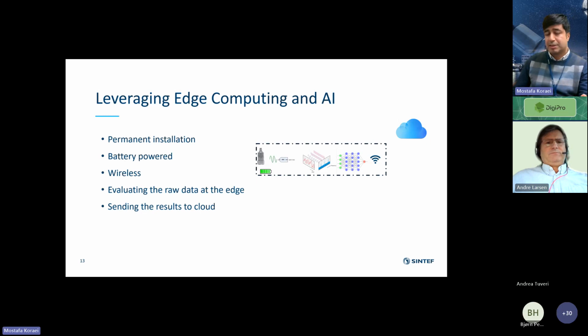Yes, the good thing about vibration analysis is that vibration can travel through structures. So if we have a system that is deployed on several units, like what we did in the Rail CBM project, then you can detect vibration that is not necessarily coming from the unit that you are observing. In that project, another customer came to our customer, Bane NOR, collaborating with Montana, and they asked for that data. That is very valuable for them because the vibration that we detect is coming not only from the bogies but from the railways as well.